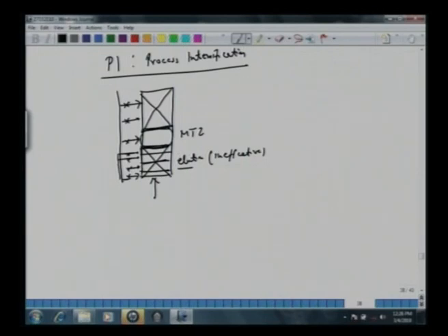So it's a wastage of this spent adsorbent. One has to regenerate this. So activity takes place only here, neither here nor here. So there's one way of process intensification which is quite interesting to note. There is a wave which moves, which represents the front. There is a propagation of this front in this direction, and one has to make the feed move like this to ensure that at any time the feed comes in contact with it, so the process is intensified. Essentially, one can show that we require a very small amount of adsorbent in comparison to the conventional process.